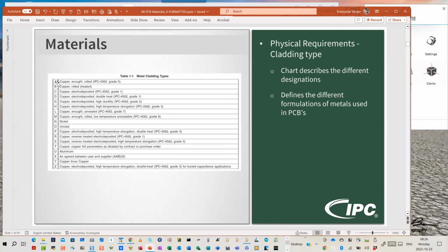The fiberglass and resin material, the core material, is then rolled through that fluid and then through an electroless deposition process or even an electrodeposition process. Copper will then be deposited onto the surface of that material, at which point the copper will have a much thinner, tall, vertical crystalline grain structure. So it's a simple, basic electro or electroless deposition process.